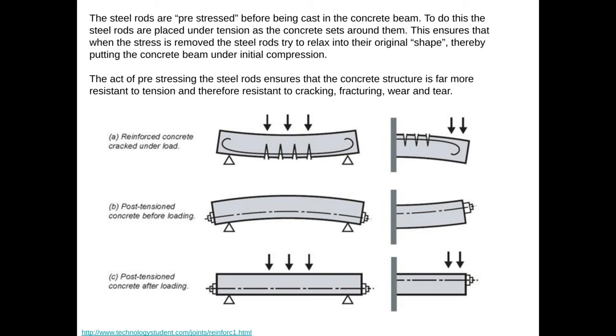That initial compression that the concrete is under before any force is applied to it increases the tensile strength of the concrete beam, and it ensures that the concrete structure is far more resistant to tension and therefore resistant to cracking, fracturing, and wear and tear.